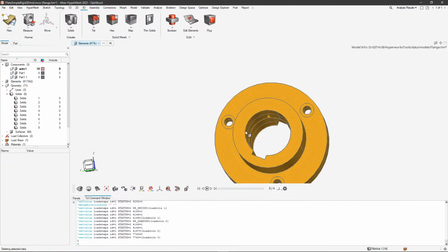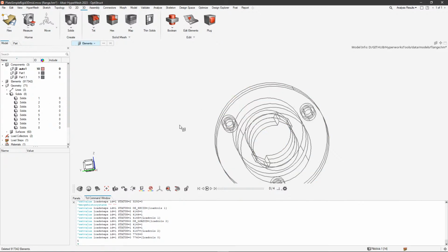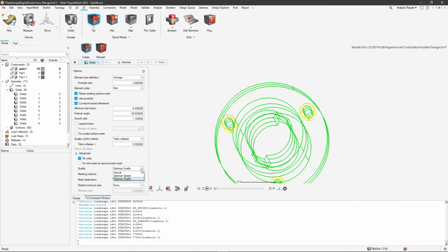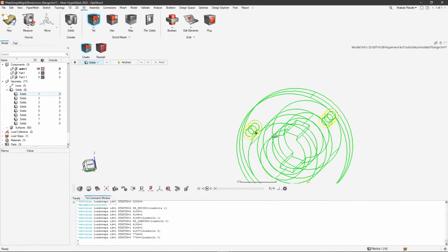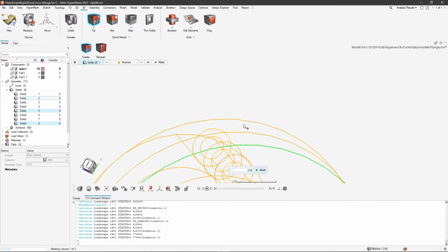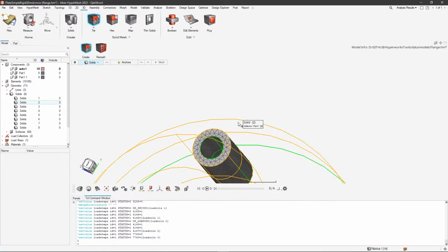Okay, let's do that again. And let's maybe try to select also the order of doing the meshing. So TED mesh create. So here, that should be it, right? TED collapse greater than 0.1, maybe greater than 0.3. Yeah. Something here, optimize quality, that's good. Yeah. All right, let's start with those components. Let's just do one. Let's see how this turns out. It's a little bit strange that it takes so long.